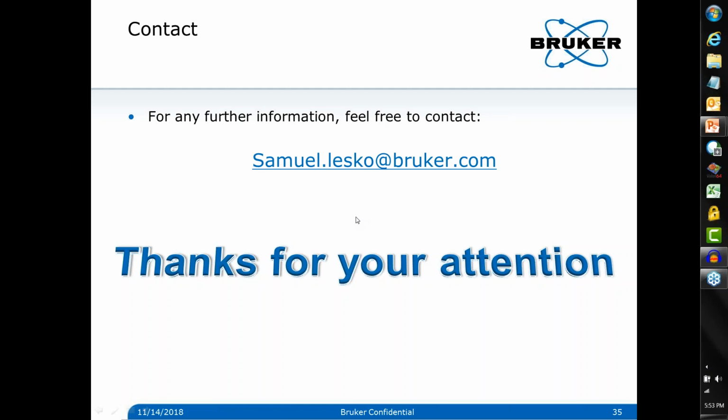We could potentially go to much lower roughness values, going to a 50x or 100x objective, but this will shrink the field of view so much that, again, focus variation will not be applicable, in the sense that it will take an hour to get the right area scan, while it will take a few minutes for white light. So it's all a question of balance of what we can grab in terms of the best technologies.